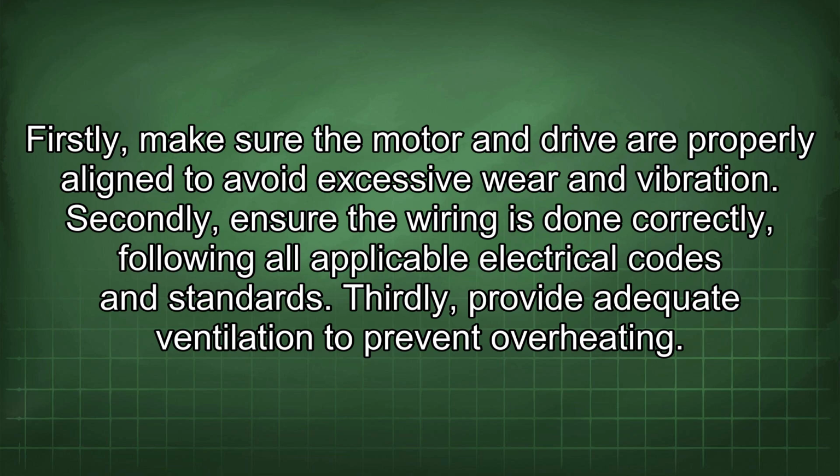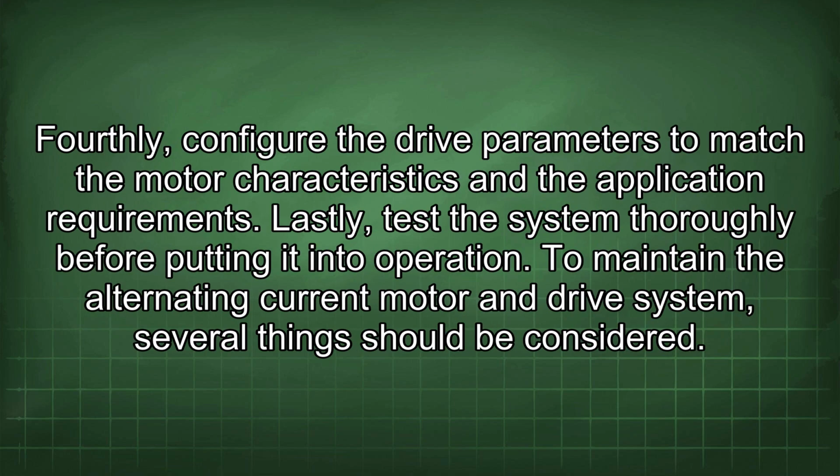Secondly, ensure the wiring is done correctly, following all applicable electrical codes and standards. Thirdly, provide adequate ventilation to prevent overheating. Fourthly, configure the drive parameters to match the motor characteristics in the application requirement. Lastly, test the system thoroughly before putting it into operation.